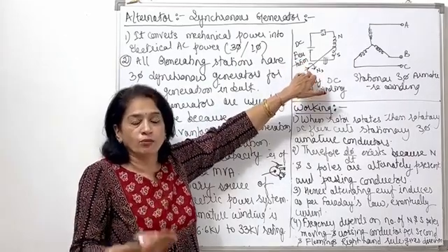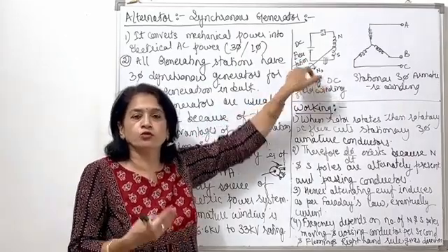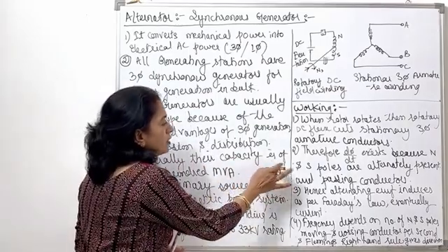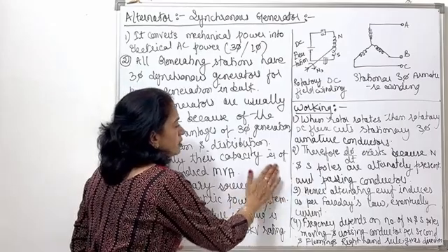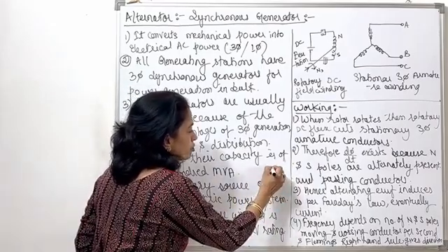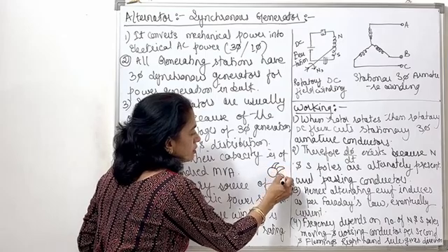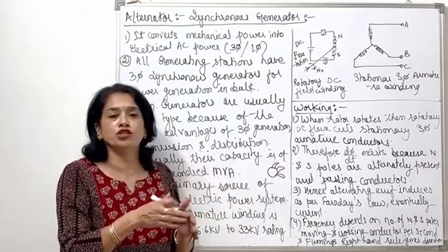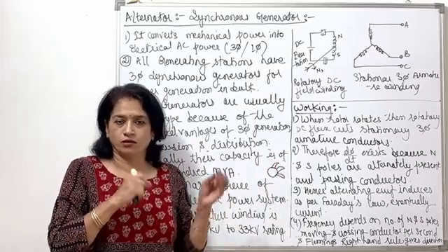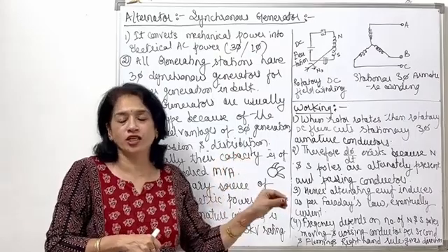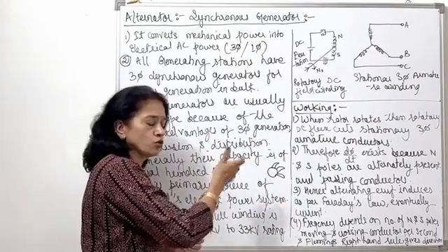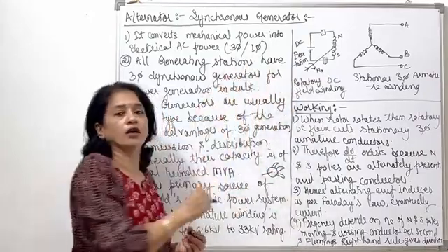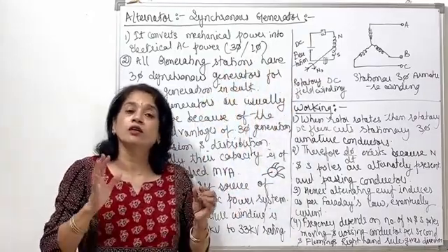What makes the rotor turn? We utilize turbines. A turbine is a flywheel kind of thing with blades, and I can draw it again fresh for you. These are the blades given over the rotor of the turbine, and over these blades, through a jet, either water is thrown or steam is injected. Because of that it starts to rotate, and the turbine's rotor and our synchronous generator or alternator's rotor are shafted together.